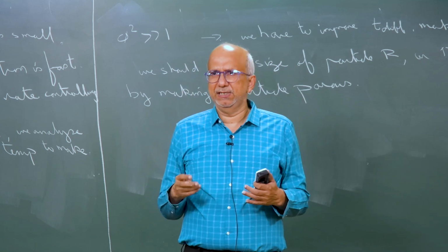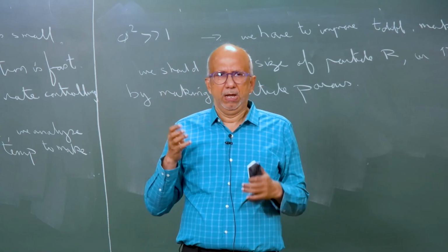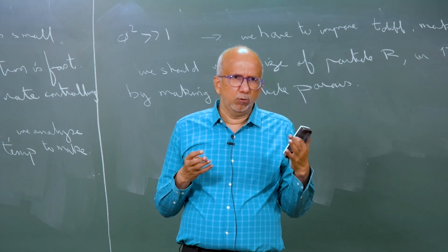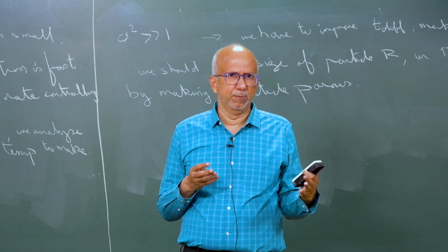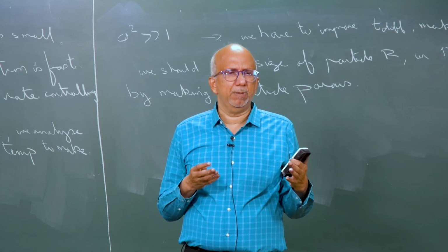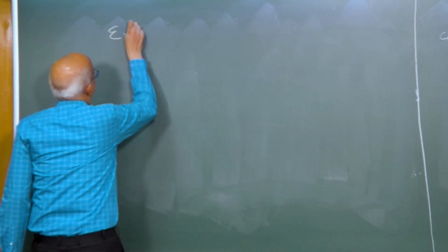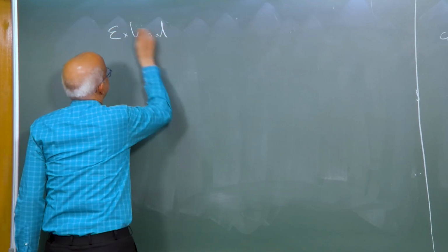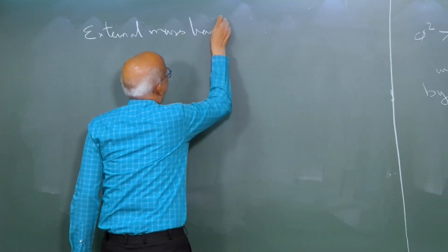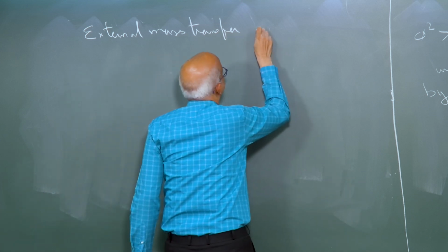There are other challenges. If you reduce the size of the particle, the pressure drop will become higher, okay. So you have to look at the overall picture, but right now we are only looking at the interplay between reaction and diffusion. I want to talk about the next aspect, which is external mass transfer effects.